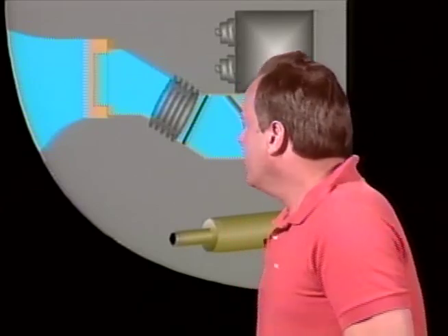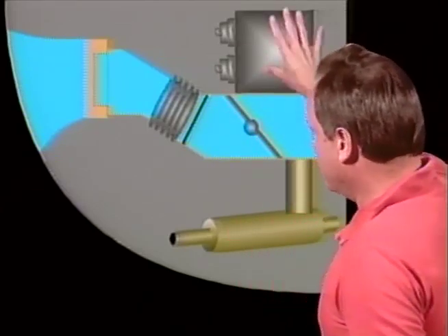Now, sometimes, if you want to make sure that the fuel-air mixture is totally vaporized, you can increase vaporization by circulating the fuel and air mixture through passages in the oil sump on the way to the cylinders themselves. So on small aircraft engines, you need to know fuel vaporization may be increased, and I'm giving you FAA magic words here, by circulating the fuel and air mixture through passages in the oil sump.